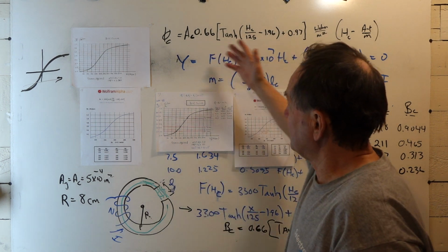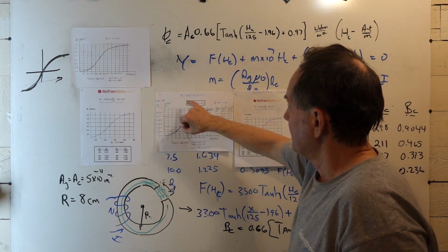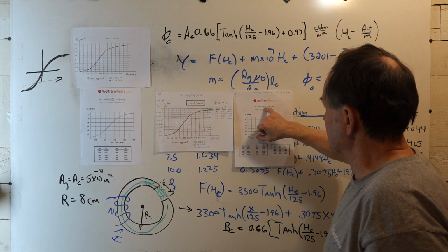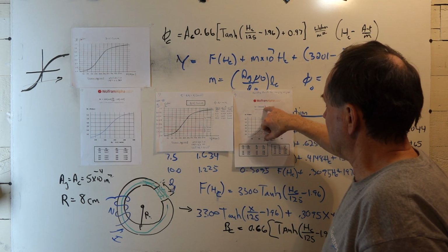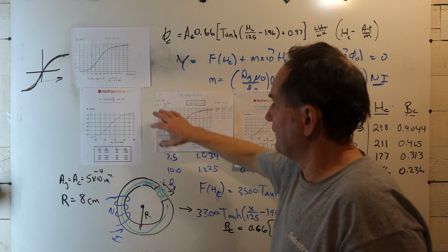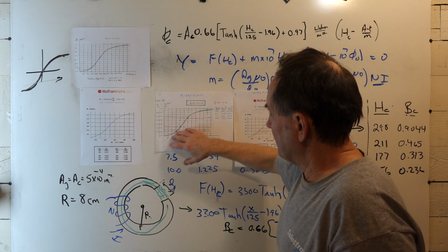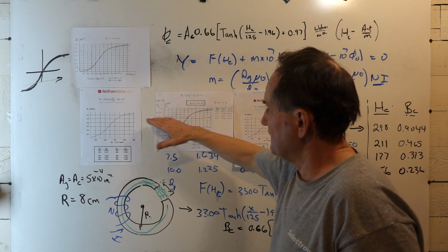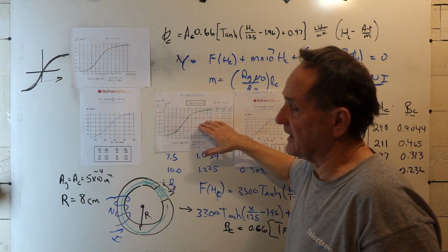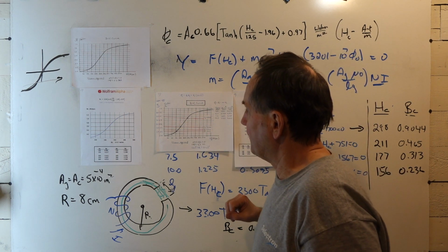We can do it analytically if you can manage to come up with an expression for the magnetic flux density as a function of the magnetic field intensity in the core material. You can solve it graphically, where you have the BH curve and you put the flux equation for the air gap plotted on the same graph, and the intersection points give you the operating point.